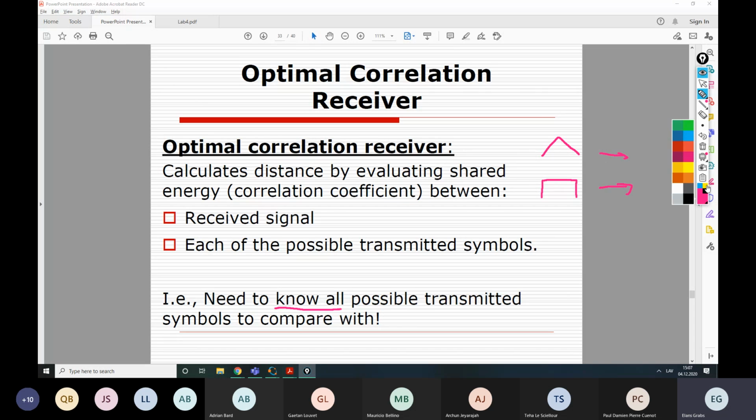And furthermore, when we have received that signal, which usually happens with some delay, we need to incorporate that delay as well. So it's unacceptable to compare like this. No, it will not work, right? So we need to actually apply a correlating time delay and compare correctly. That's the highest difficulty, especially for phase shift keying, because we need to generate the template signal accordingly.